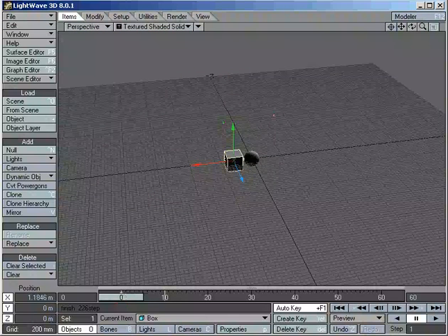That is how all the dynamics operate. You apply hard effects, soft effects, or cloth effects, then you need to have something acting on it. Some of the actions, particularly like in cloth, you can apply dynamics like gravity right in the effector. But it needs to have some action, some force that will make it change. Whether it's a collision, whether it's wind, whether it's gravity. Then it needs to be calculated.